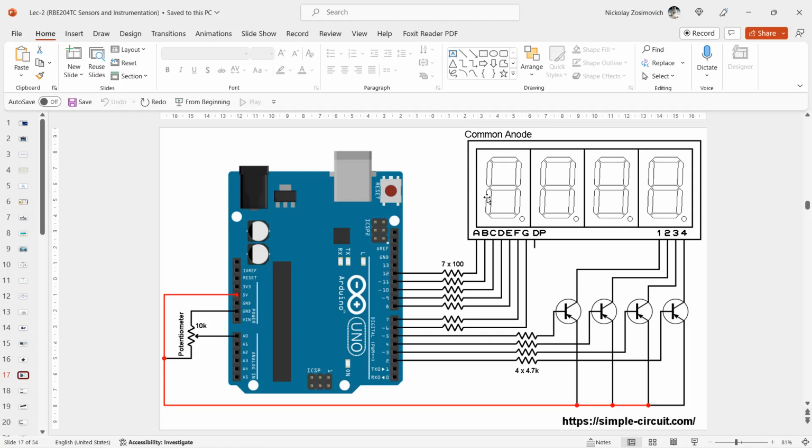Okay, so regarding the input pins that can be used for AD conversion, the controller has just one AD converter and a 6-channel multiplexer, and these pins can be used as general purpose input or output pins as well. It is also possible to use an internal pull-up resistor on every input pin, and thus, in our simple cases, eliminate the need for additional components for interfacing sensors.